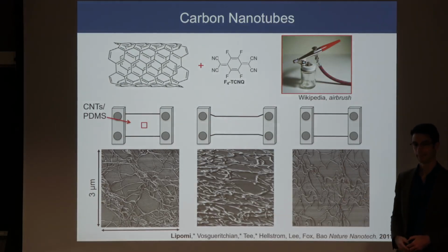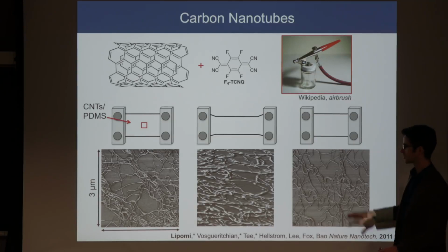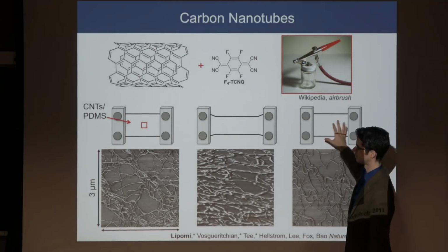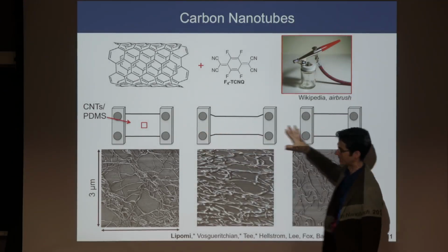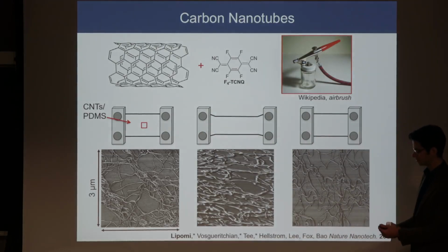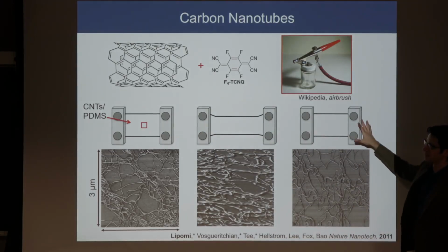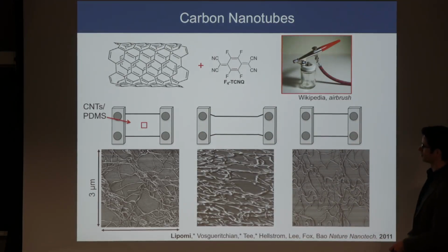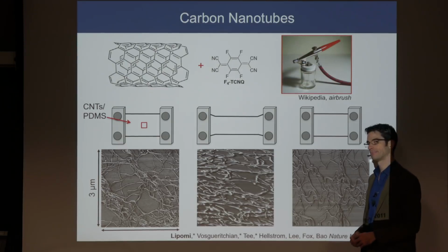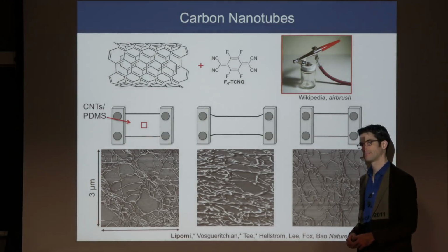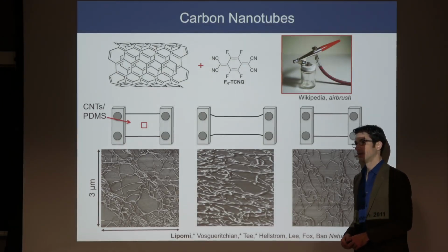Yep. Are these deposited on a stretchable medium that's used to do this testing? Yeah, these are deposited on PDMS, which is a silicone elastomer, and it's been modified by ultraviolet ozone oxidation.